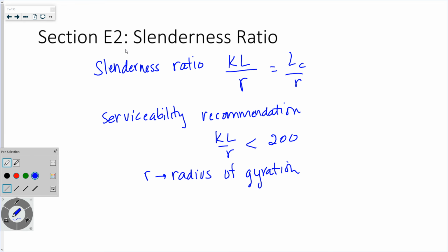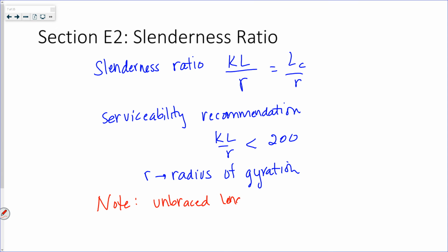Now here's a big note, and we're going to talk about it later. Note, your unbraced length L may be different in different directions. And I'm going to show an example of that in the next slide.